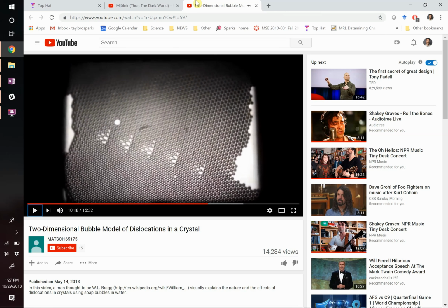The reason it lines up, first off, the reason that it went to the right, is that it didn't feel that repulsive force anymore, because now that thing was brought below it. And moreover, it feels now an attraction because the tensile region below it lined up with the compression region, and so they line up. This is pretty rad, right? The fact that we can see this in bubble rafts is helpful, but this is also happening at the atomic scale. This is a pretty good model to simulate how atoms interact.